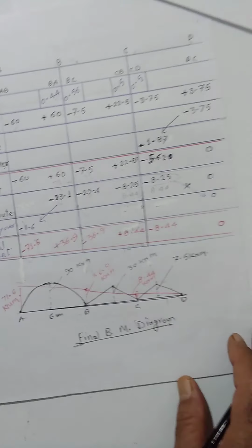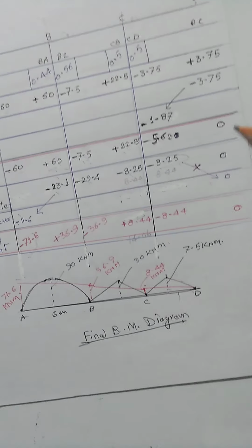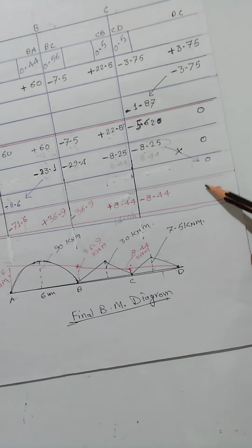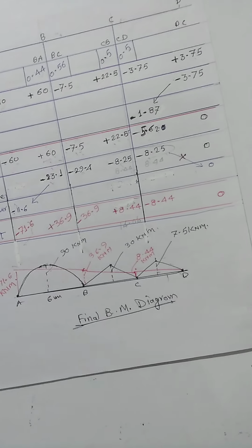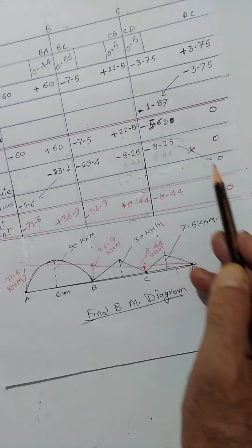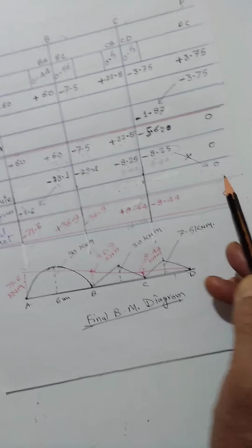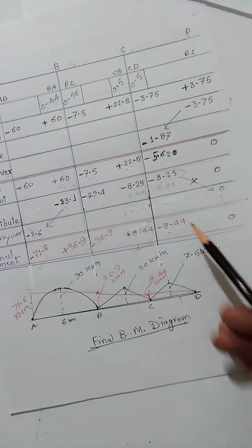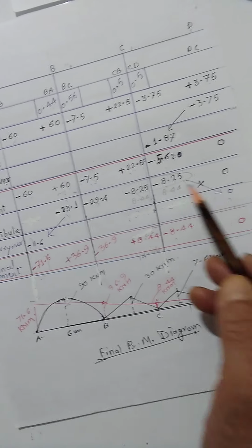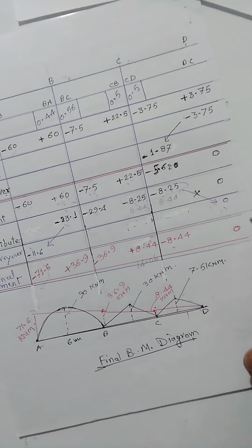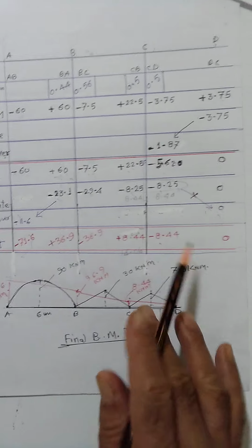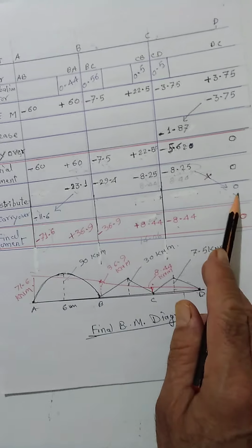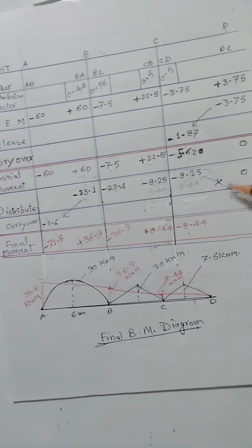One thing is to be kept in mind. We know that finally when D is simply supported, the moment is to be kept 0 throughout. Of course, it could be carried over, but if we carry it again, we will have to make it minus 0 and bring it back again. So it is better not to carry this over to this side, and the matter ends. So if something is there, don't carry it over here, because finally it is already 0.